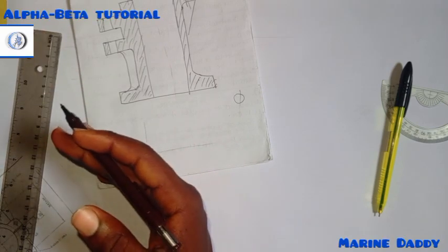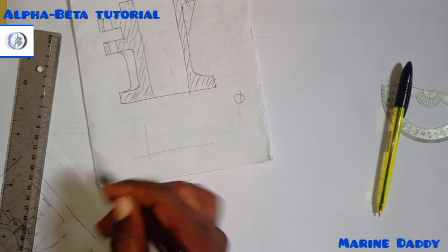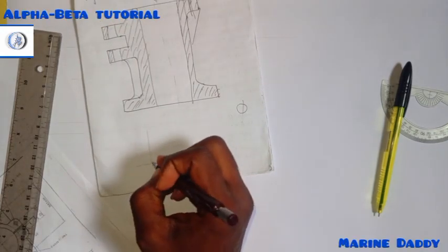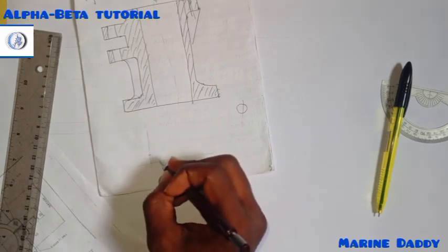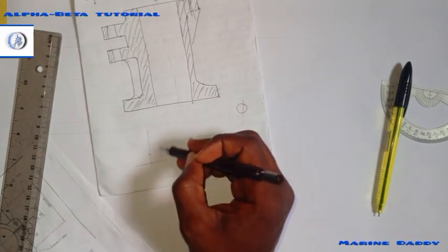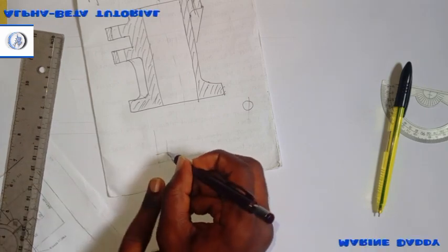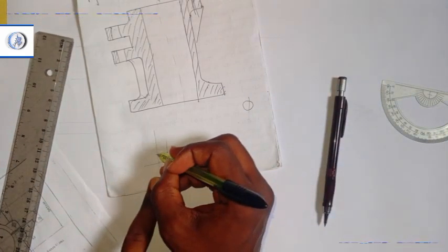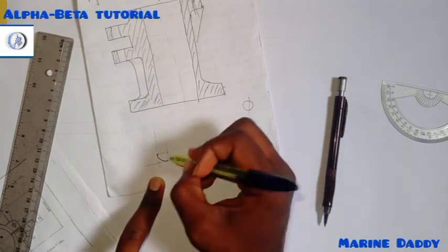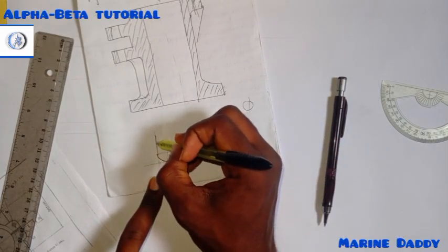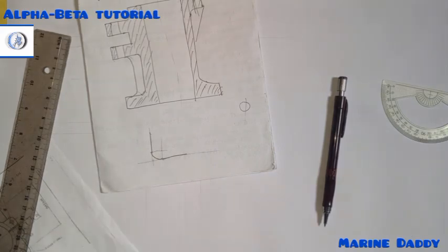Sometimes there are some questions that will tell you the radius of that curve. So let's say the radius is 2 centimeter. So you measure 2 centimeter at the vertical, measure 2 at the horizontal, then draw a straight line like this to intersect here. So after intersecting, from this place, open your compass to this place, you can now cut it like this, and this will give you what you are looking for. Then you just draw a straight line here. So no matter the position, this is how we do it.